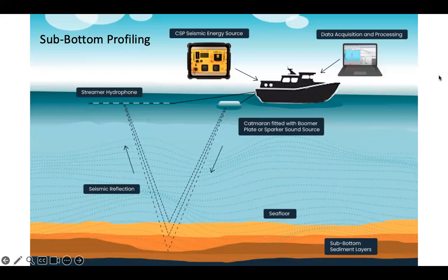So, to start off anyway, sub-bottom profiling is a geophysics technique and it has a lot in common with traditional geophysics techniques such as reflection seismology and also multi-beam sonar, which is effectively a very short wavelength version of what I'll be talking about today.